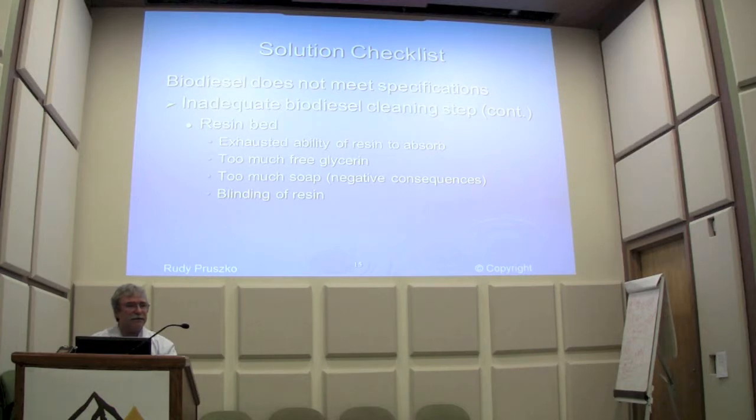Yes. How do you make sure you don't have too much free glycerin going through your Amberlite or Purolite that you're using? Is that just really with your settling process, you gotta make sure it's... Yeah, that's why I said when you're doing your final settling, let a little biodiesel go in with your glycerin as opposed to the glycerin with the biodiesel.